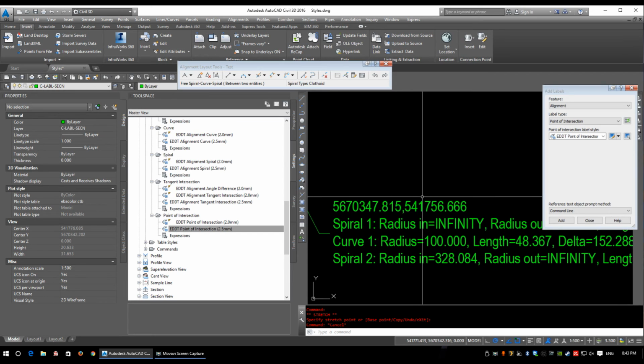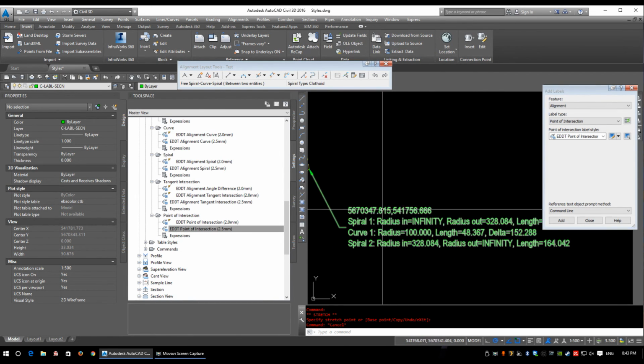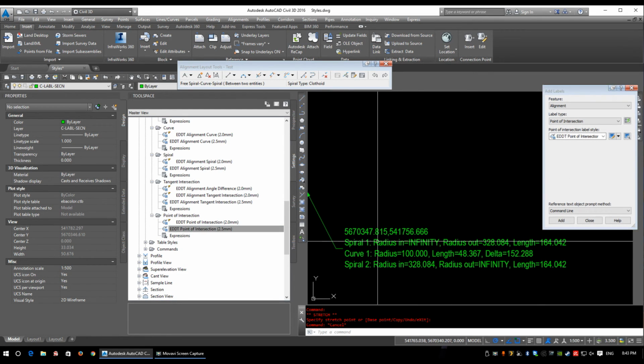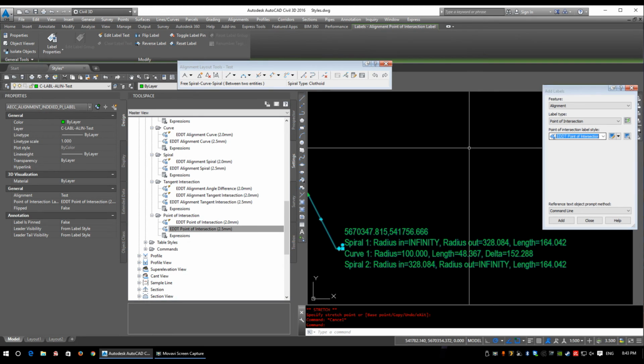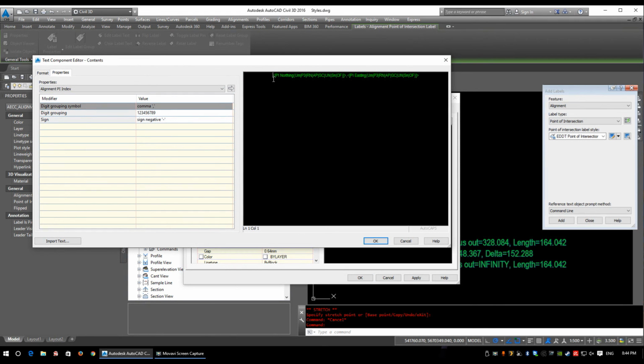We have our easting, we have our northing, and again they're all messed up, so we'll quickly edit it. So that's the 2mm one, yep. We'll just right click, edit it. Actually, northing is first, so northing, easting, and we can get rid of the comma.